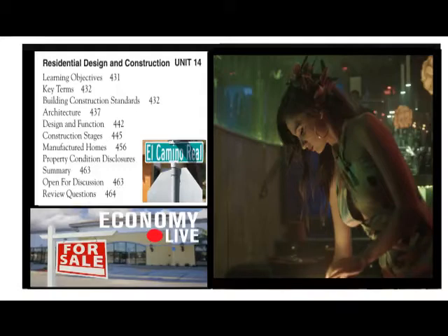Orientation is generally best when the greatest window expanse faces south, with a deep enough roof overhang. South-facing windows allow the winter sunlight in yet are shielded from the summer sun. This is particularly important in desert communities. Figure 14.2 shows this principle at work.